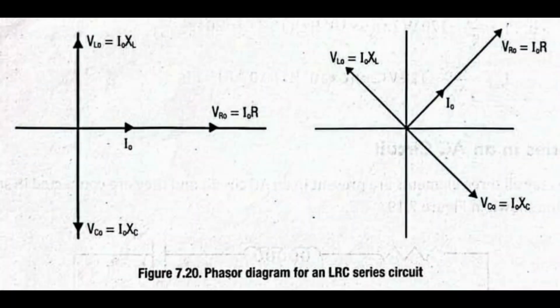When resistance is very small, this becomes a pure LC circuit. In a perfect LC circuit with no resistance, energy doesn't dissipate. It oscillates back and forth between the capacitor's electric field and the inductor's magnetic field over and over at the resonant frequency. This is LC oscillation, the heartbeat of every radio oscillator and TV tuner ever made.